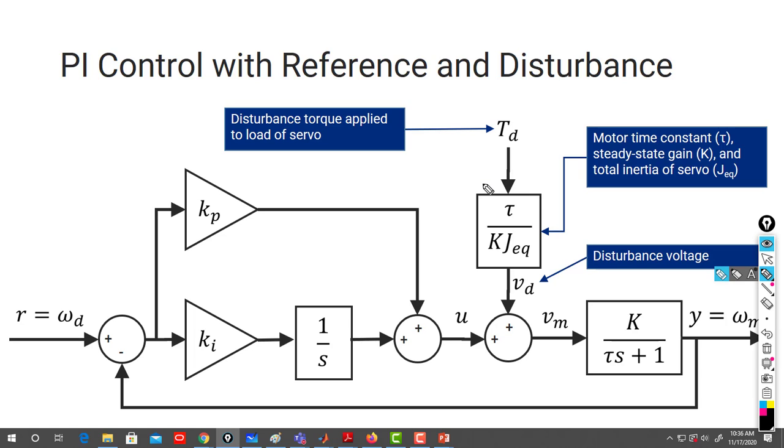The dynamic of your physical system will be converted to a voltage. Because here we are doing modeling, I know the dynamic of the system. If you know the DC motor modeling, how it's modeled, the electrical and mechanical part, combine them together, you know that there is a relation between the torque and velocity, between the torque and the voltage,